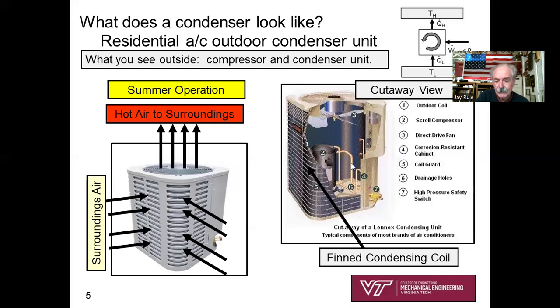What else can you see here? It does turn out that inside this unit, which is essentially just a hollow unit, that's where the compressor is located for your whole house air conditioner as well. So the compressor, that loud compressor, is located outside. The refrigerant compressor is located outside within this unit. Basically, the thing you want to see here for the condenser analysis is these condenser coils on the outside of this big rectangular box.